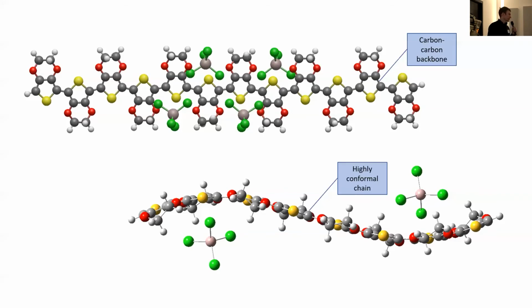That's really driven this research down a more conducting polymer theory route. You do see PEDOT in supercapacitors, and you can imagine a tangled mass of PEDOT with a high surface area. This redox reaction then works really well because you're not actually trying to drag the charge carriers through the bulk of the electrode.